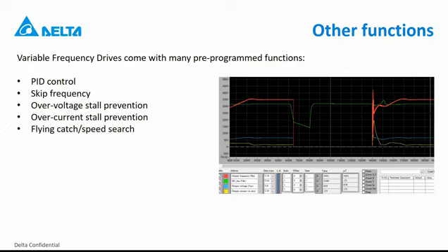And you definitely do not want your application to have to wait for a minute or longer until the fan reaches a complete stop so that you can start it once again. So what the drive can do is, when it's starting, it can detect the frequency at which the motor is currently running, and then it can just catch it from that particular frequency.